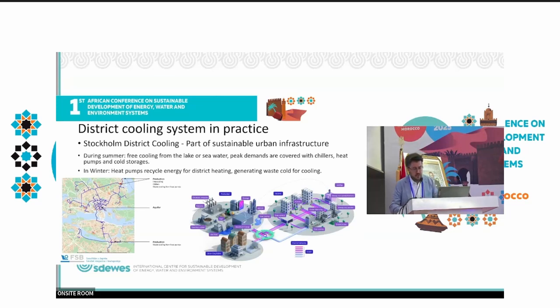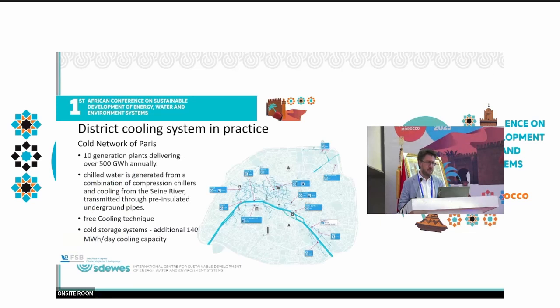So, integration with district heating, using cold supply from large heat pumps providing heat to district heating. The largest heat pumps actually use district heating and district cooling from purified wastewater. It's one of the biggest systems, around 220 megawatts, around seven big heat pumps. Here, the cold storage is actually a cavern, which is a very interesting technology.